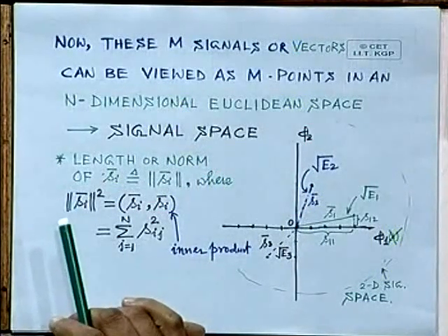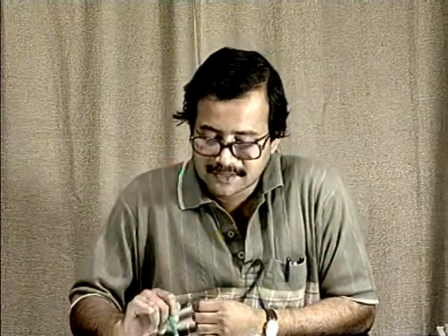Amplitude of the signal. Now, my question is, should this concept, the length of the vector, be somewhat useful? Yes, why not? And his quick guess is that it is related to the amplitude. A better statement: it is related to the energy. We will see shortly that it is nothing but the square root of the energy of the corresponding signal.